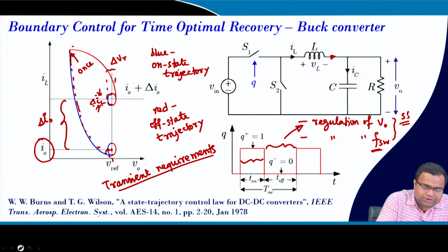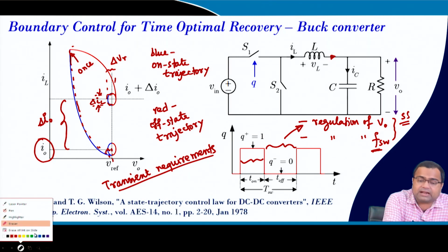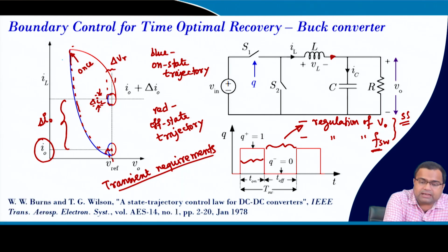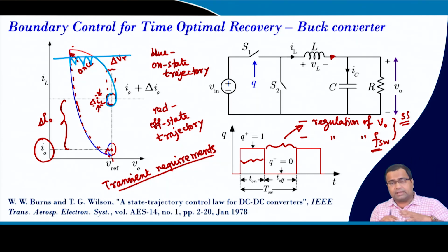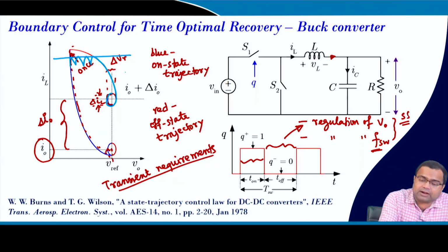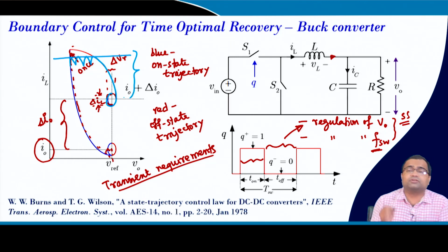One of the problems is that you will have a current limit. Then what you can do is turn on here and it will go through multiple switching actions, and finally come back to here. That part we will discuss in a subsequent lecture, under constraint on the current limit, because you can see there is a high current overshoot. So, this is my current overshoot.